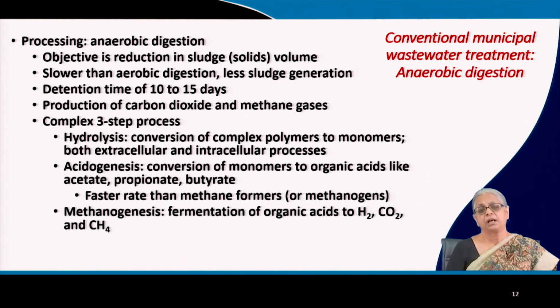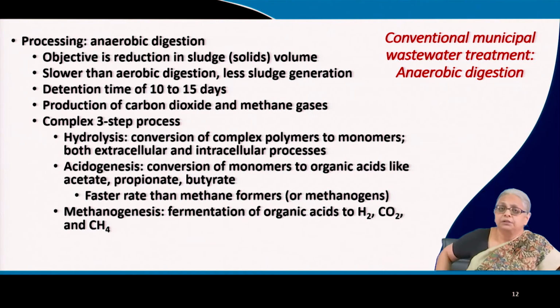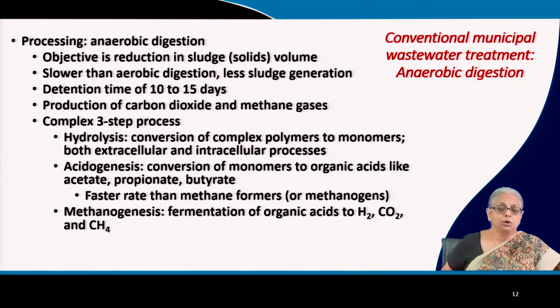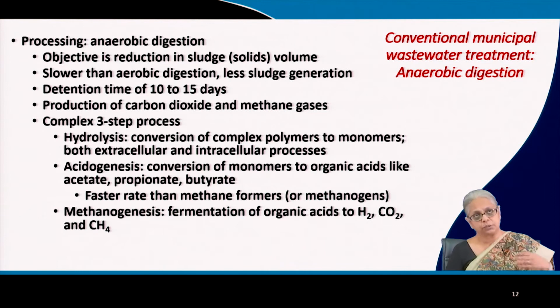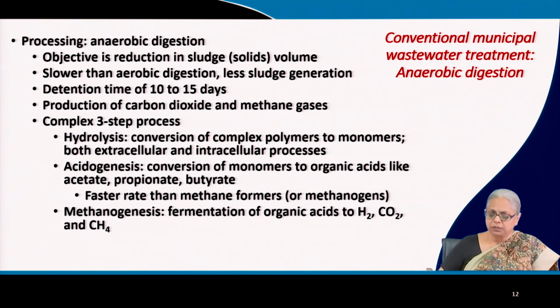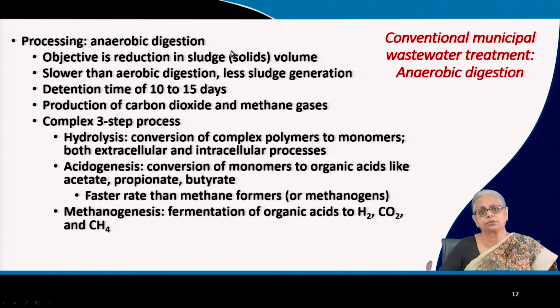Now, if you can imagine a large city and a wastewater treatment plant for such a city, that's a huge amount of both water as well as material that needs to be taken care of. So, by increasing the solids content, if you can go from 1% to 5%, 10%, 20%, 20% seems to be the highest, you can reduce the volume in terms of the water content enormously.